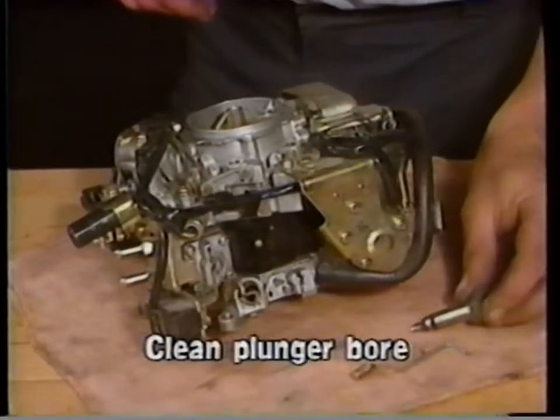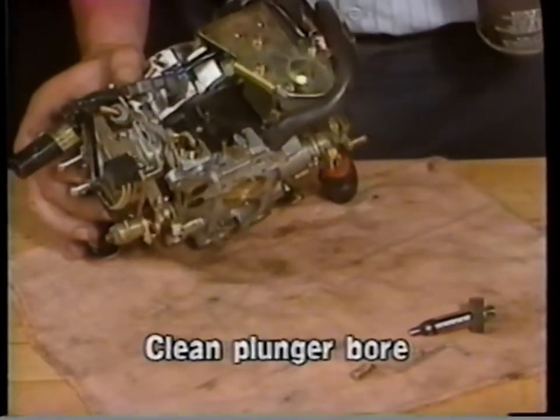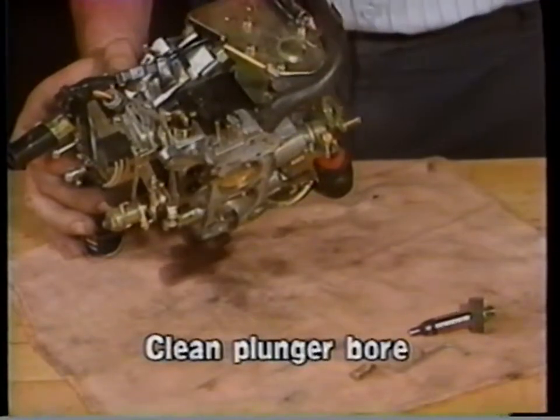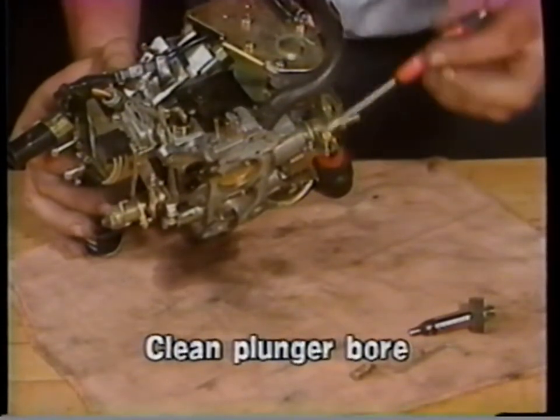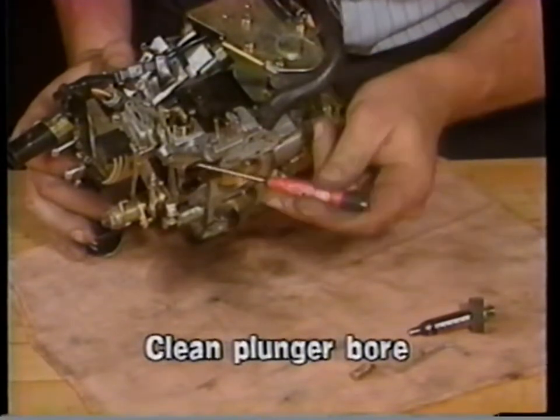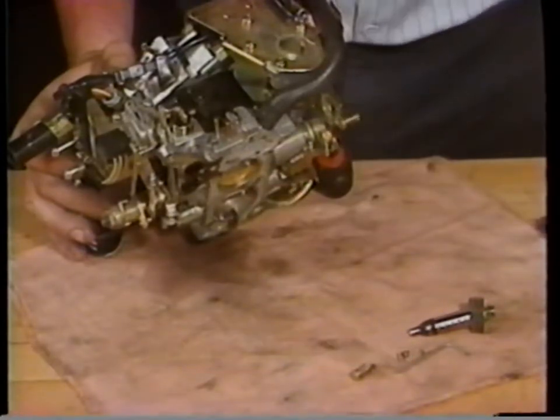Next, clean the plunger bore with Mopar brake and carburetor parts cleaner or equivalent. A small screwdriver can be used to loosen carbon deposits in the passages in the underside of the carburetor. However, do not use any type of sharp implement in the plunger bore. Scratches in the bore will cause carbon to build up more quickly.